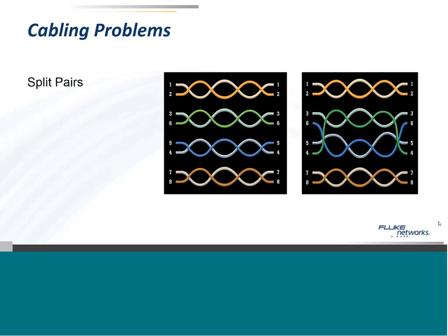There's an app note out by the NBASE-T Alliance that we helped write that tells you about the kind of testing that you need to do on Cat5e cables to verify if they will support 5GBASE-T in addition to 2.5GBASE-T. So if you want to run 2.5 gig on your Cat5e cable, you shouldn't have any problems if it was certified and you know it's Cat5e. But if you want to run the 5 gig, you may have to do a little bit of retesting. The testing that's required is around alien crosstalk.